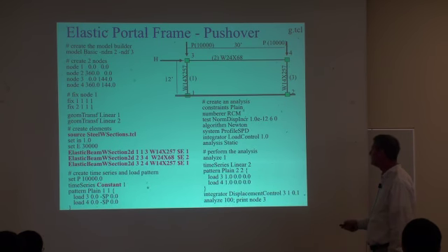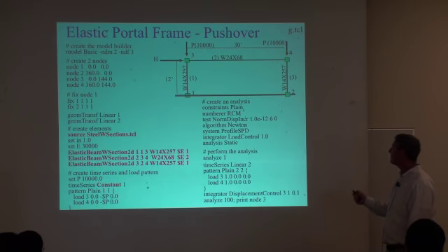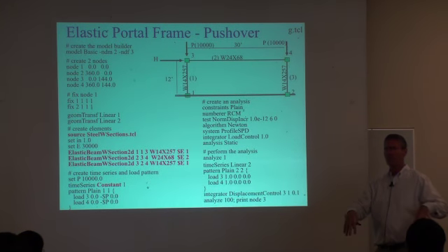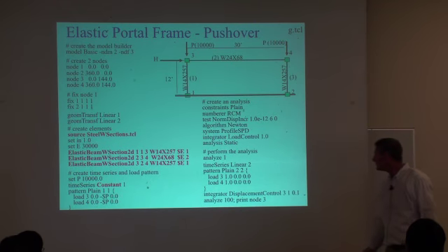So what I've also done here is I'm showing the analysis. After I create the vertical loads, I'm just going to do one analysis. Load control 1.0, and this is basically my gravity analysis. Typically what we do with our buildings, our structures, we apply our vertical loads first as a constant gravity load. We pre-impose them on the building before we hit it with the earthquake. So here we're doing basically the gravity analysis. These vertical loads are staying constant and we apply them.